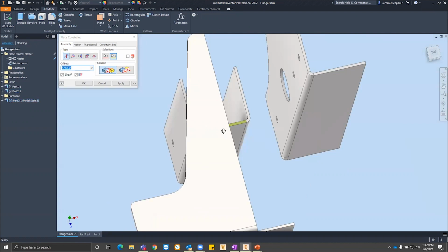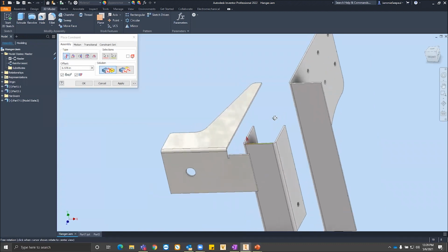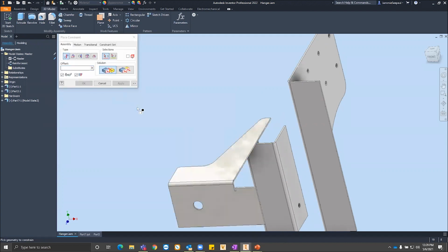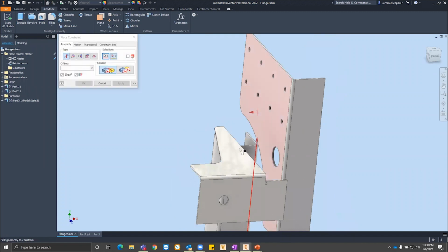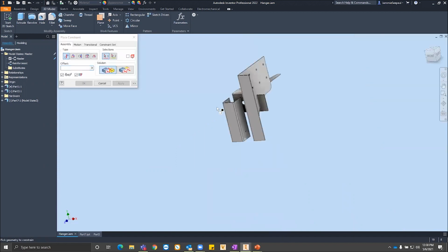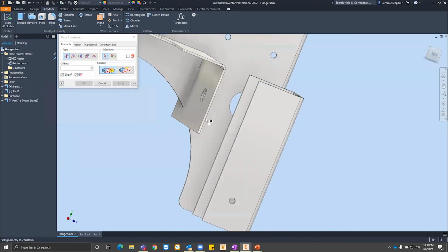Also, a little tip: in Inventor, you have these little glasses, which is a preview, and this little kind of measuring tape. If you have this checked, it'll keep your item exactly where you had it whenever you go to make a constraint. If you have it unchecked, it'll just assume a flush mate. I like keeping that checked so I can watch the part move, but it's really just your preference. Sorry for spinning a lot. I know it might make some of you dizzy.